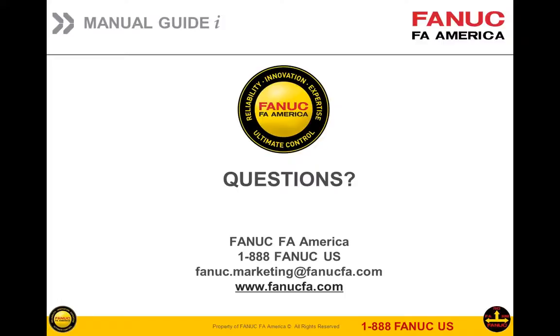Okay. All right. I think we can get these last couple questions in. Does the software allow for the size of the tool in the tool table? Yes, it does. And that sort of goes back on the question we answered earlier, Mark, where it was asking about tool nose radius comp. Because regardless of whether you turn on tool nose radius comp with a G41 or G42, it does look at whatever data you put in your tool offset table. So that ties into where we talked about it's important that you get the right data in that table. Yeah. Okay. Good.